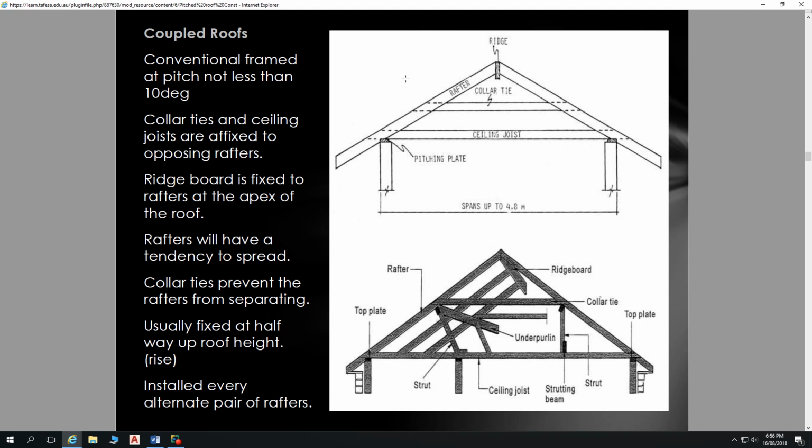And I've been inside one roof that was doing some very odd things in the eaves, and what we could see from the eaves was that there was separation of the collar tie and the ceiling joists. Those joints were coming undone and becoming elongated. So it's not something that's very common, but that serves a very important feature. And for that reason,